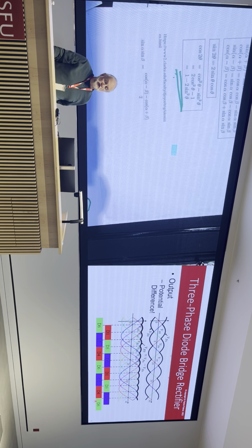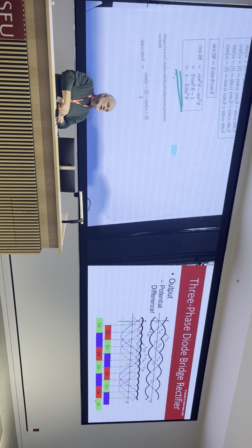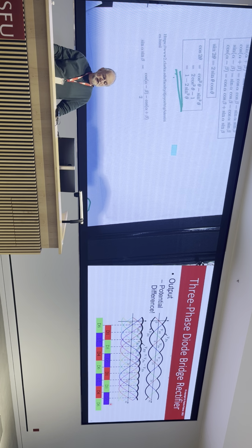What do you notice? You notice they're out of phase by, I'm going to get this right, 60 degrees. How do I know it's 60 degrees? Because one cycle is three of those bumps, that's 360. So this is 120, so halfway is 60.